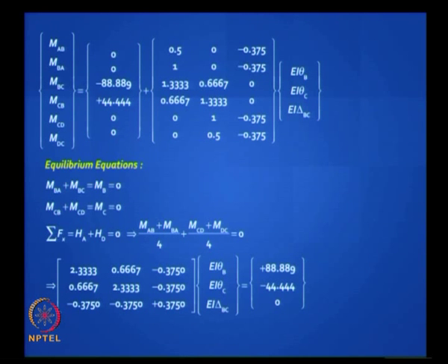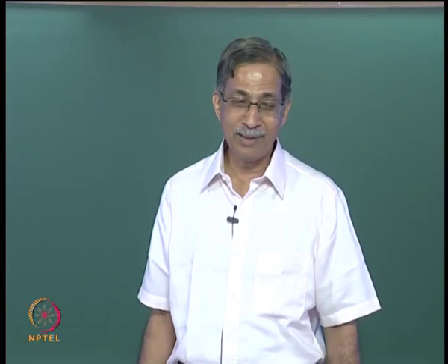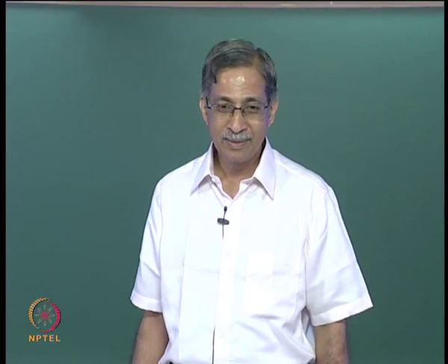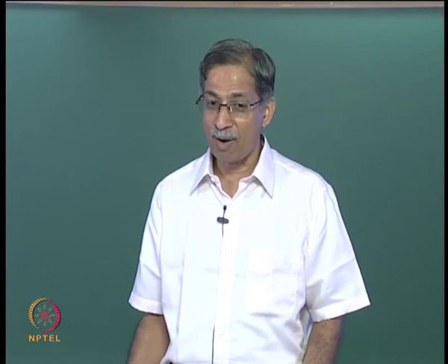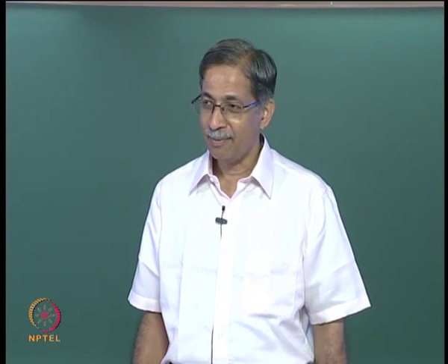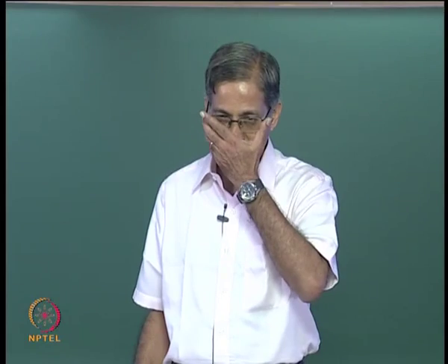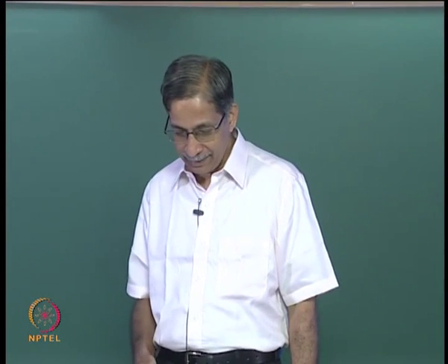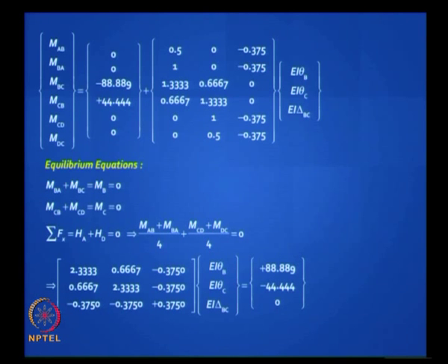What is that matrix? Displacement methods are stiffness methods, not flexibility methods. That matrix is a property of the structure. What is that matrix called? Well, it's related to the stiffness matrix, and the beautiful part about this is the vector that you get here is caused by the loads.